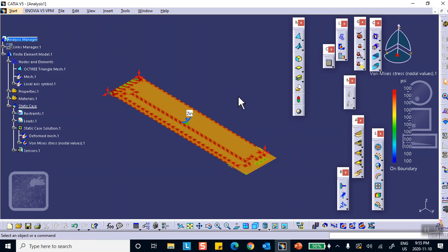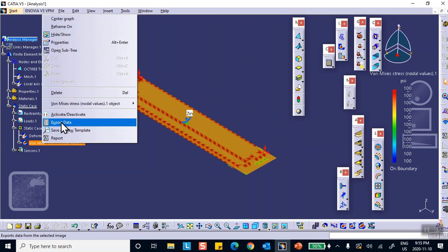There we are. Okay, don't let these weird dark red spots fool you. Look at the numbers. Everything is 100. Therefore, as I expect, the von Mises stress, the only stress that's acting in this problem is the stress in the x direction. There's no other stress in y direction. There's no stress in x, z, or there's no shear stresses. So it's not surprising that the von Mises stress is also 100. Now, let me deactivate this. Actually, I'm going to delete it.